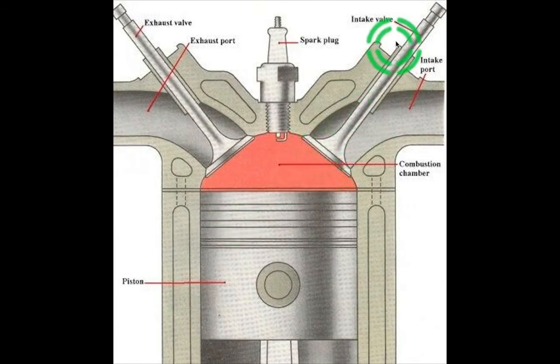So that's why the valve spring is actually so hard that regardless of what pressure you're applying here, it will not be able to push this valve inwards, right? Only a camshaft with a mechanical force, a certain degree of force, can push this down. So yeah, it also consumes a lot of energy because the camshaft is driven, but let's not get into that.